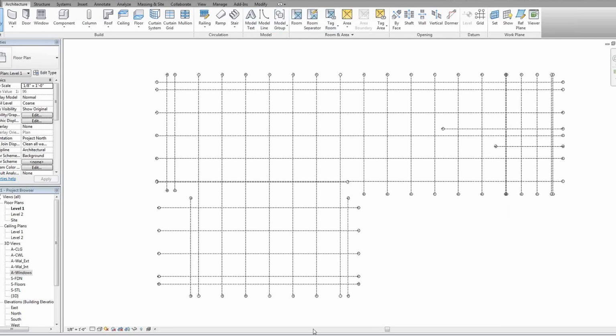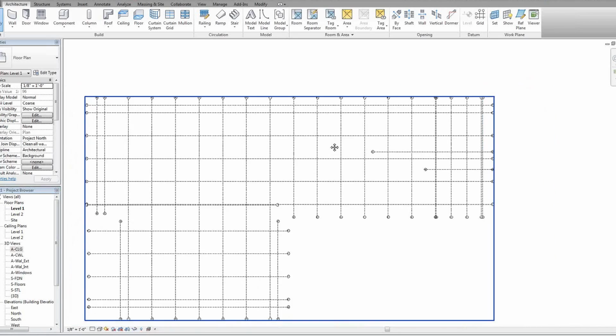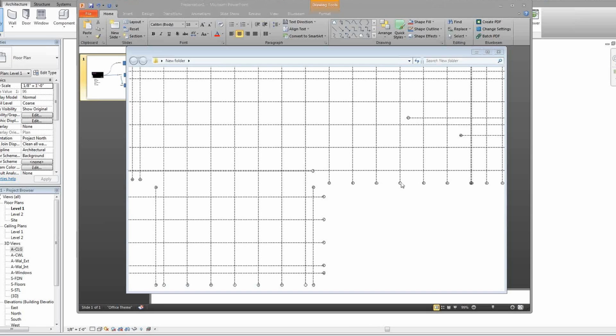Yeah. When you're in this mode, when you're getting Revit files and you're the person on the team that's distributing the information, every time there's a new Revit file, you have to go update the backgrounds and dish them out to the team. So it's once a month. Now that we've got this set up, it takes 10 minutes. You open it up, you export the new backgrounds, and you update Oxygen. Okay. But it's definitely a maintenance task that you've got to stay on, because you just want to make sure that the team always has the latest and greatest of everything.